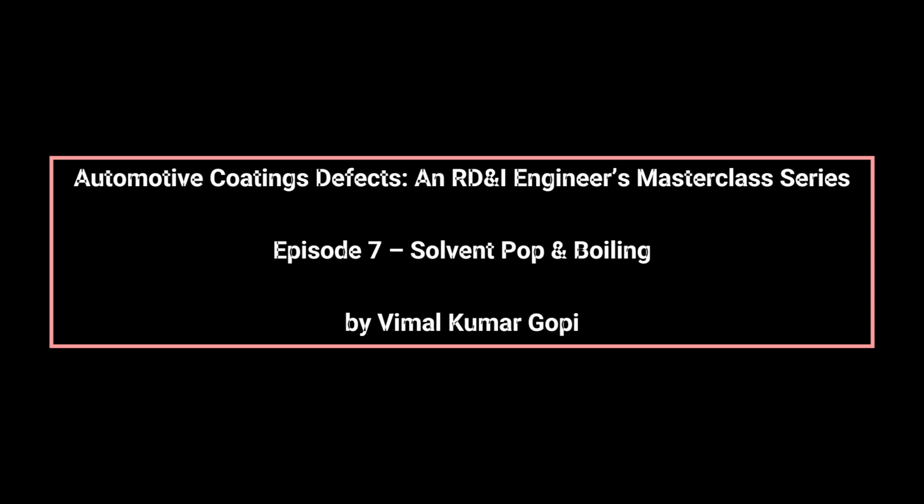Third, review solvent blend selection against booth and ambient temperature. Fourth, evaluate oven ramp profiles rather than peak metal temperature alone. Plants that control these variables eliminate solvent pop reliably without endless formulation changes.